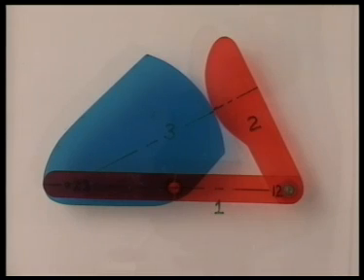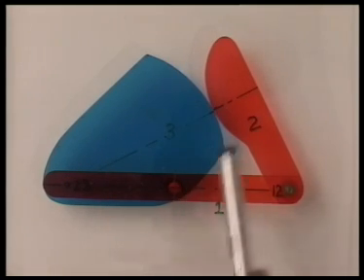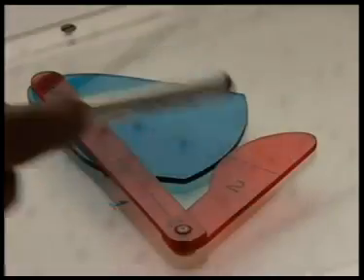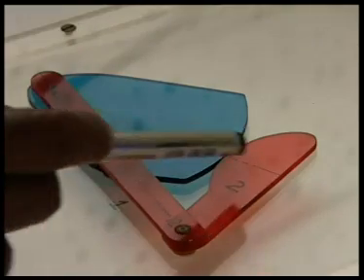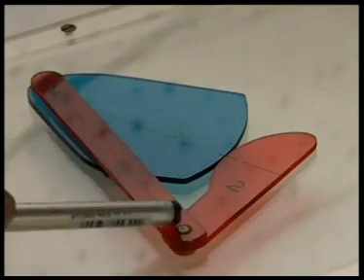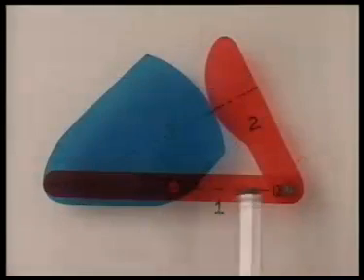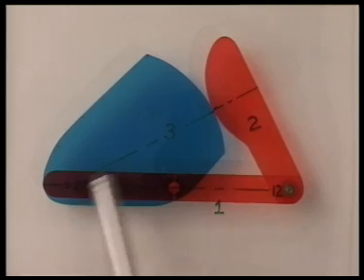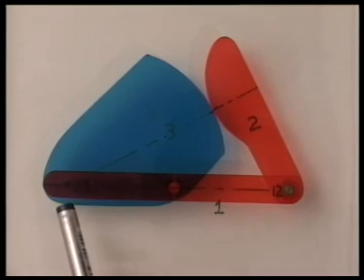And we also know from the Aronhold-Kennedy theorem that 1,2, 1,3 and 2,3 must be collinear. That is how we determine the location of 2,3 at the intersection of this common normal and this line joining 1,2 and 1,3. 1,2, 1,3 and 2,3 must be collinear and 2,3 must lie on this common normal. That determines this location 2,3.